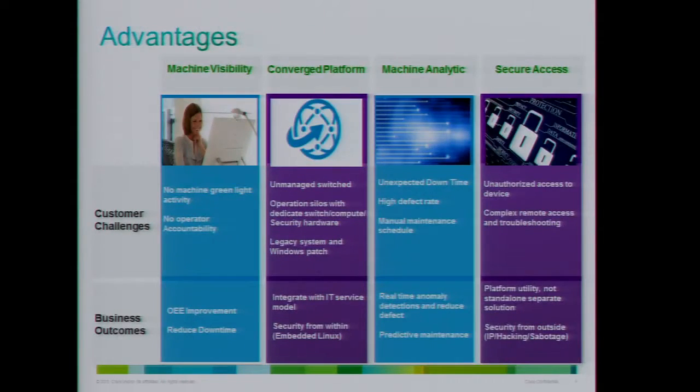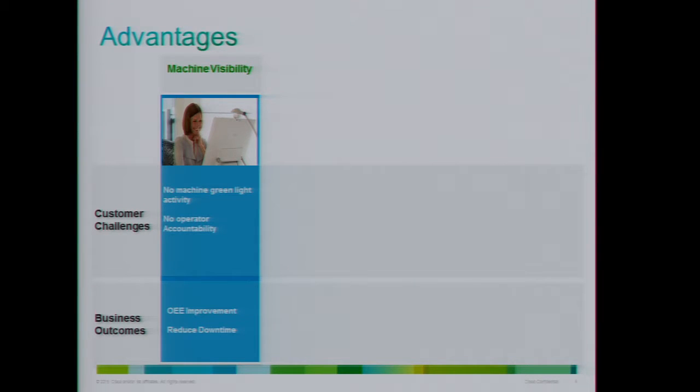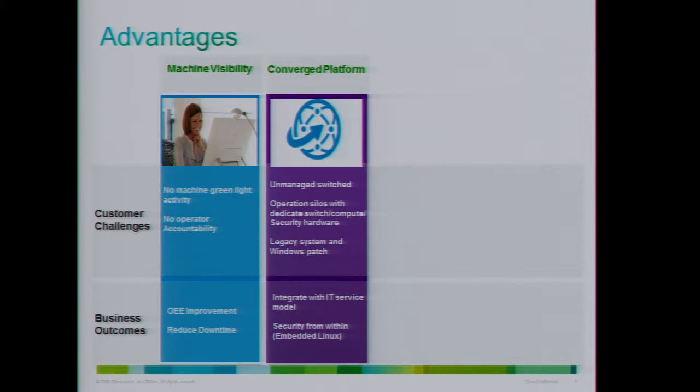You can see what your OEE application is saying to you, and based on that, you can reduce your downtime by taking immediate actions on your machine. Your machine is not generating enough data, a spindle motor is not working properly, the temperature is too high and it needs to cool down. So you can set thresholds on those parameters, and it can give you information immediately.